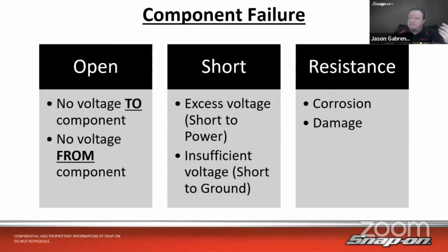So an open would be maybe I have no voltage to the component. Right, voltage supply, it's open, and I'm not getting any voltage. Many components will have power, ground, and then a signal returned back to the computer. Maybe that signal's not making it back to the computer, right? So that's an open.